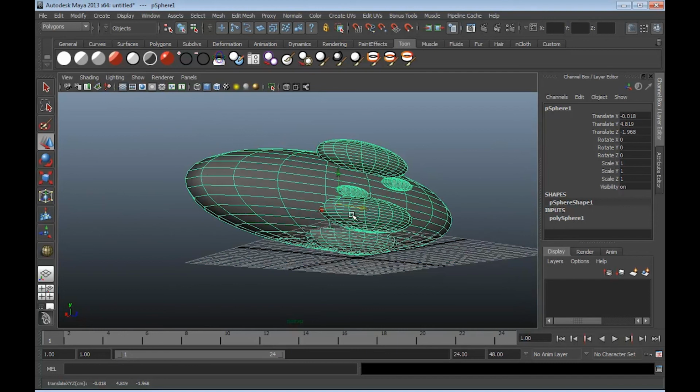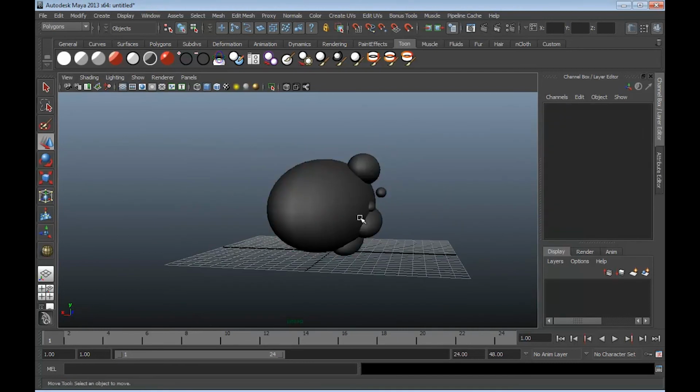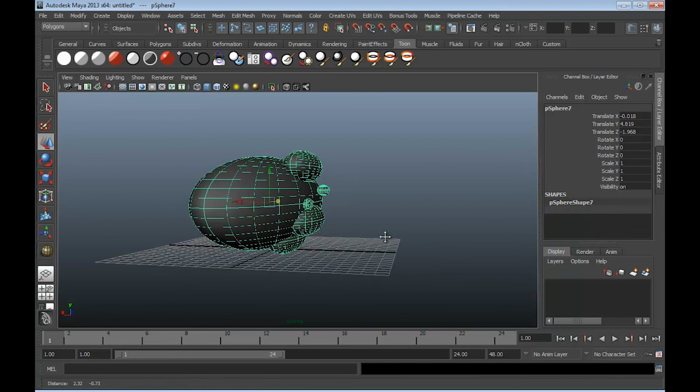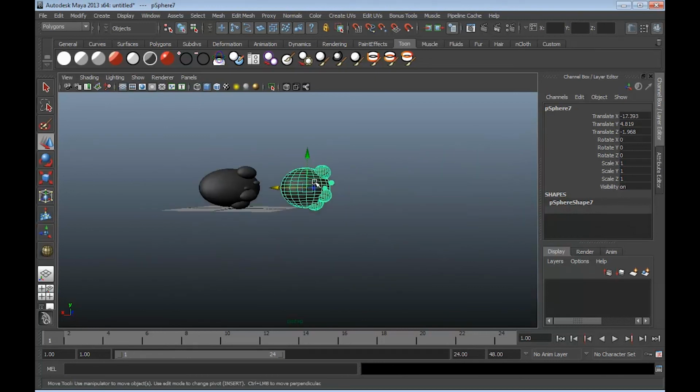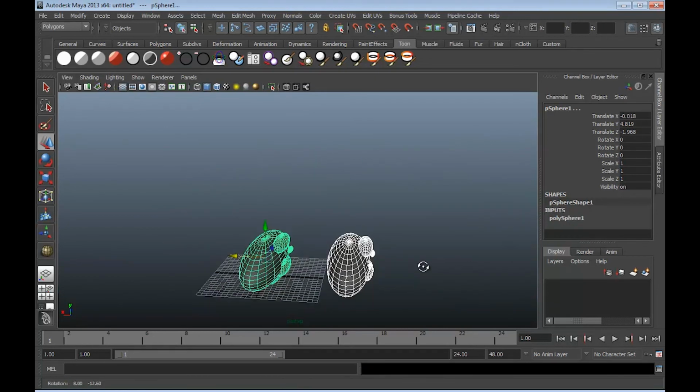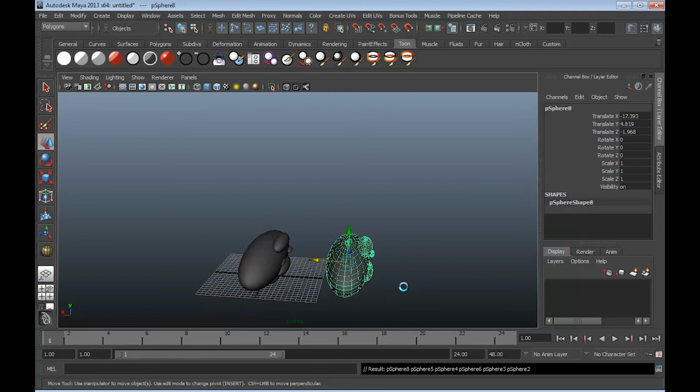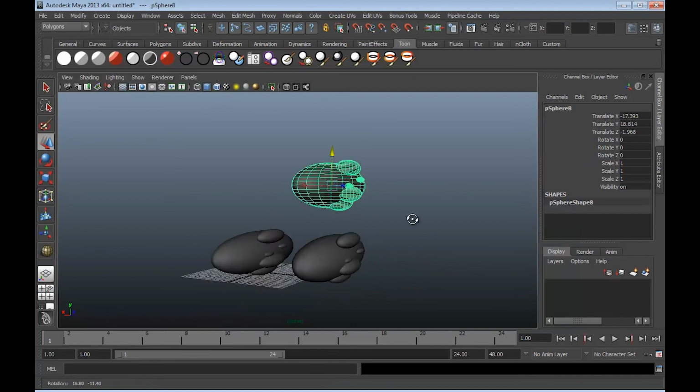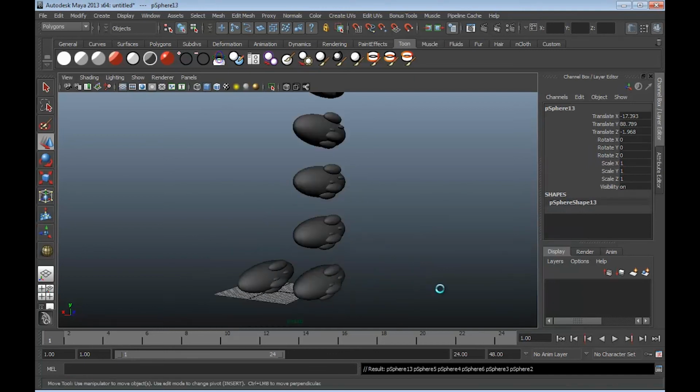How do you click, drag, and duplicate at the same time? Well, I don't know. I haven't been clicking and dragging and duplicating. I've been hitting Control-D to duplicate. And every so often, I've been hitting Shift-D. What Shift-D does is it saves whatever transformation you make. So the next time you hit Shift-D, it does it again.